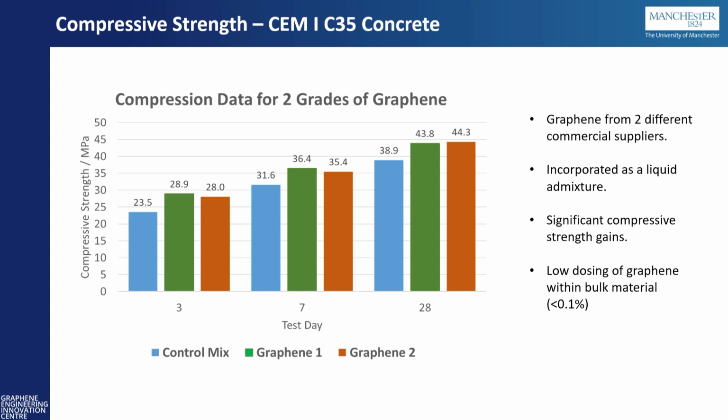What we're doing now, we started over the past year, is looking at different systems, so GGBS, looking at different admixtures, looking at different low cement concretes. Essentially what we see is we can get the C35 strength early on, almost at 3 days, certainly by 7 days. And we even surpass the design strength of the concrete after 28 days. Most of this strength increase happens at the early stages, as I said, and it does tend to plateau out.